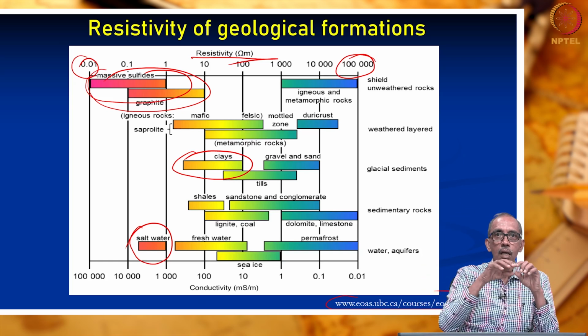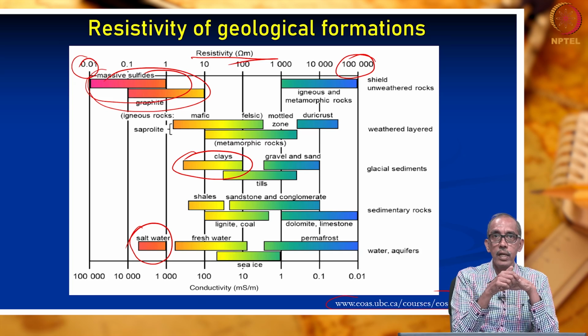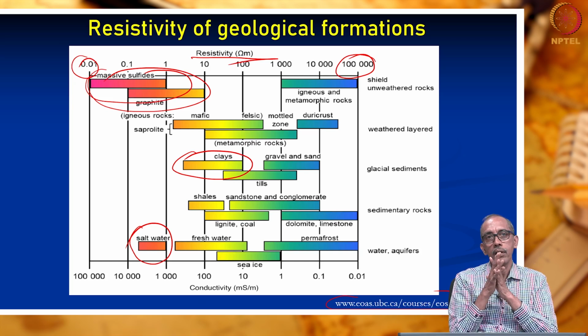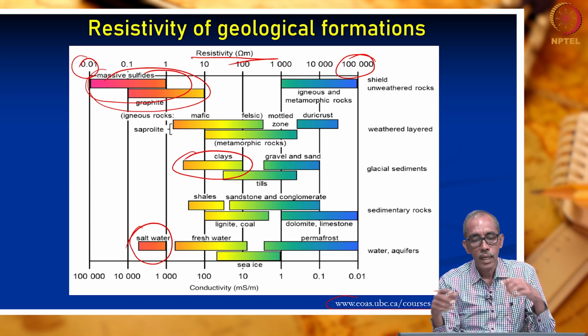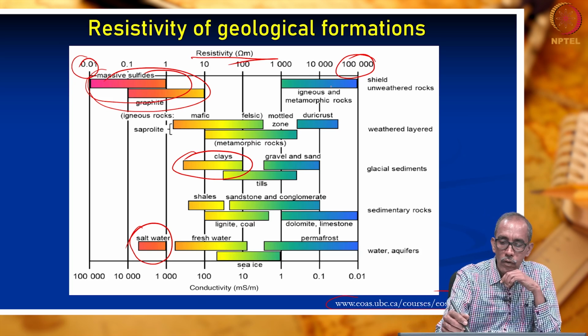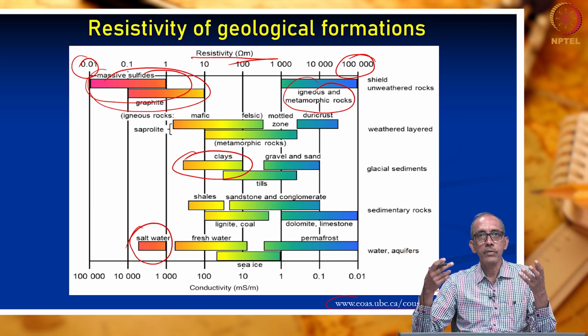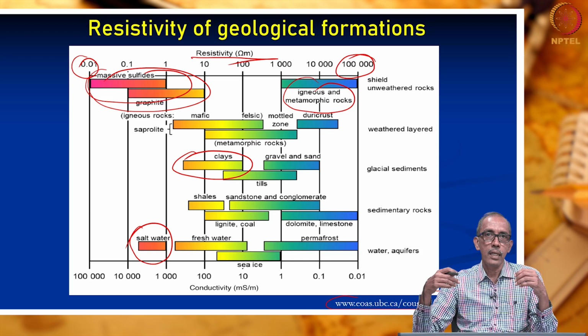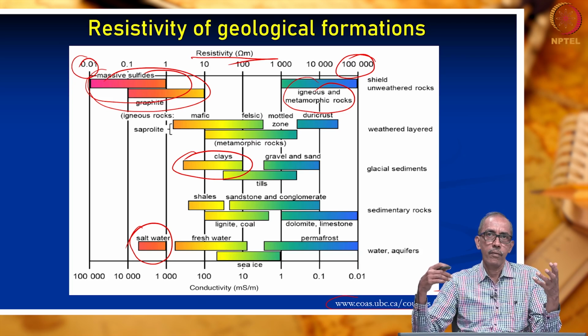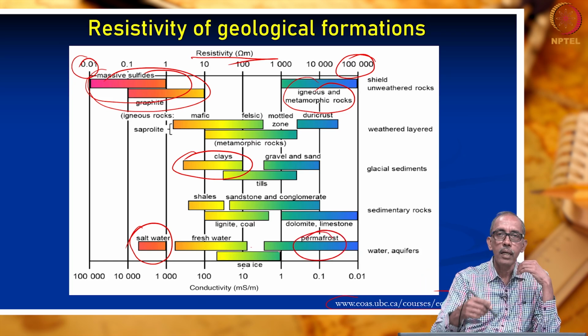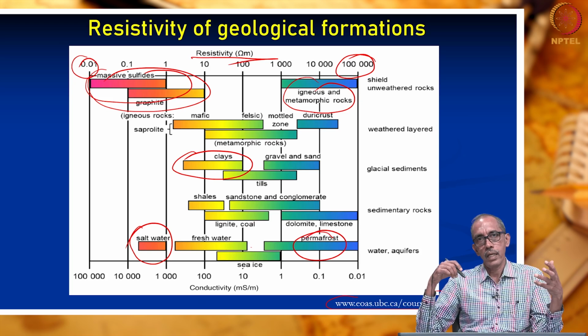At the surface, the clay may appear dry. You can see some cracks in agricultural fields during the dry period. But beneath, moisture is still retained, due to which resistivity is low for clays. How about rocks? The common rocks which we see in our mountains, or the rocks which we use as building material, have very high resistivity. Similarly, when water freezes and becomes ice, resistivity is very high.